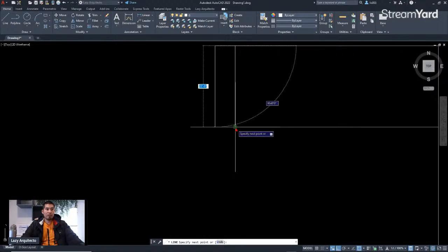So hover over this and then move your mouse to the side, and you will see an X. So that white X is called extension, and you're seeing it over there on this blue square. And again, this is another precision setting that is activated, and it's called extension. And it's very useful to draw more efficiently in AutoCAD.